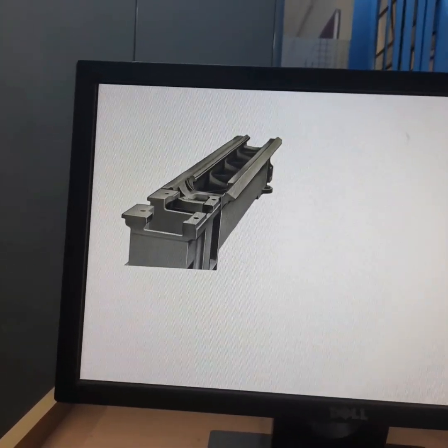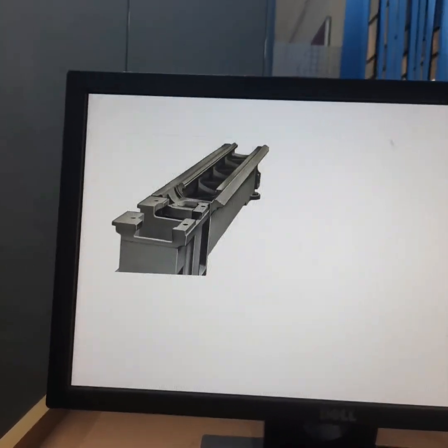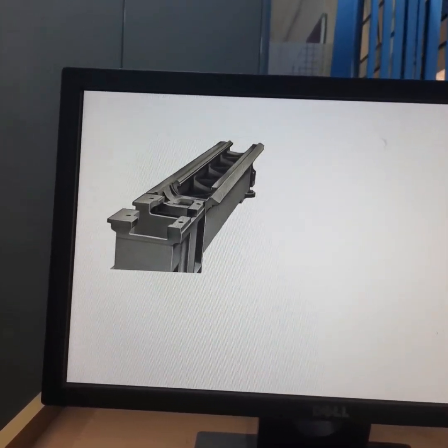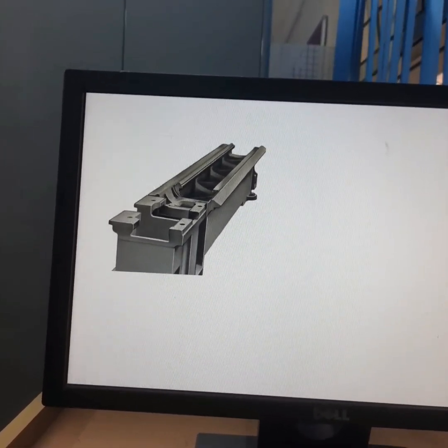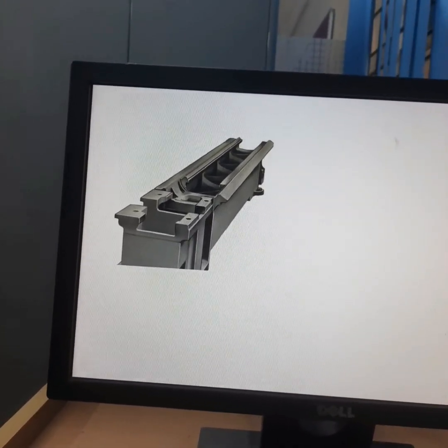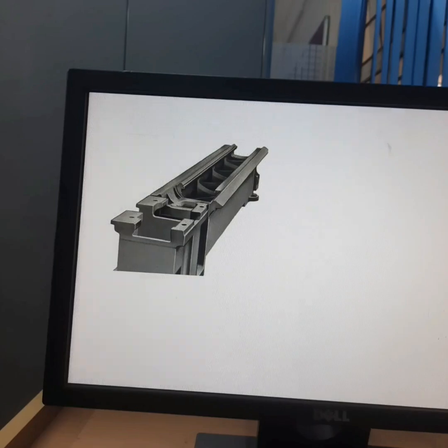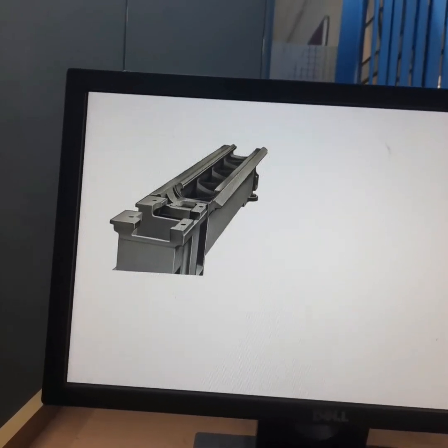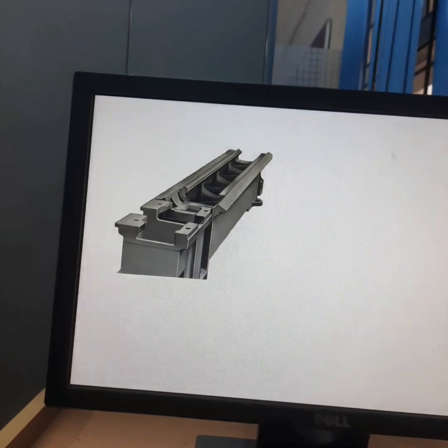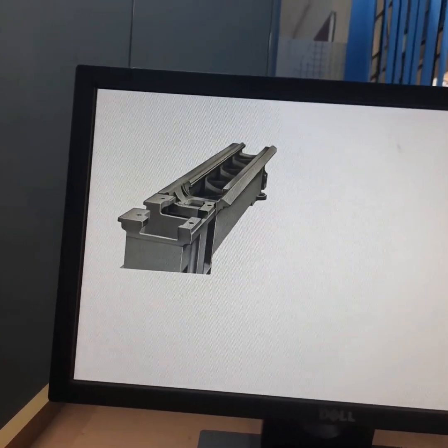So there is a need to produce the lathe bed using casting only for mass produced components. If the lathe bed is produced in mass quantities, then making a pattern and running the furnace will be the right option.